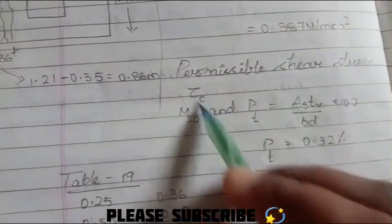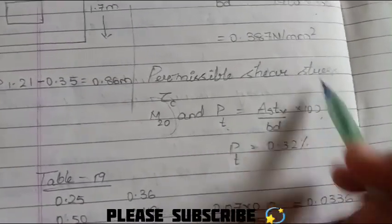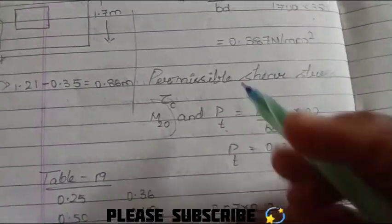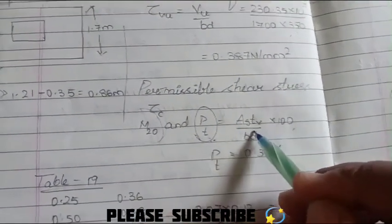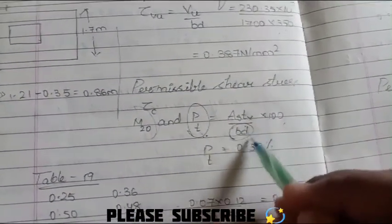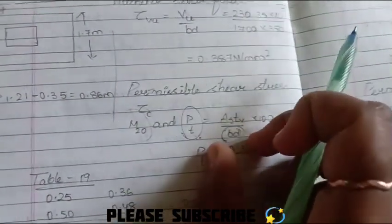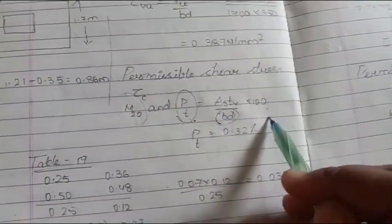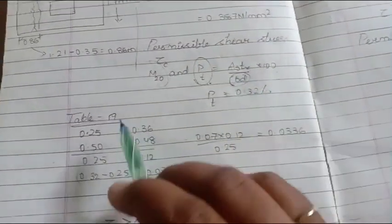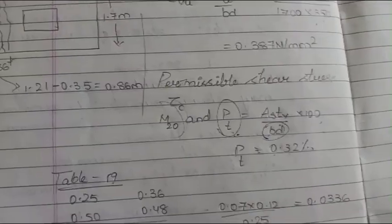So, for M20, we know the percentage is nothing but Ast by bd into 100. This is the formula. Remember pt, the percentage of the reinforcement, is going to be Ast divided by bd, the overall section. Whatever the percentage of reinforcement provided for the overall section, this is the value, pt equals Ast by bd into 100. We got the pt. So using Table 19 of IS 456, which I'll be showing you now.